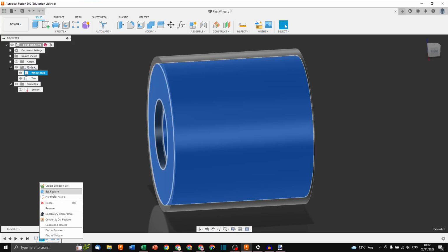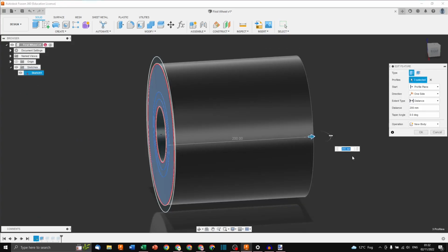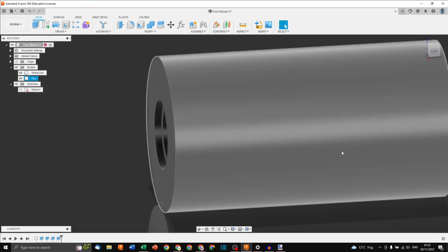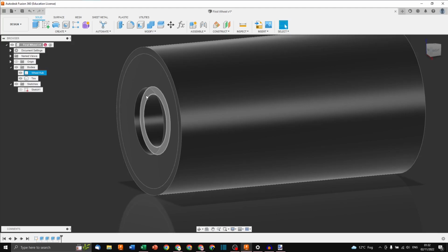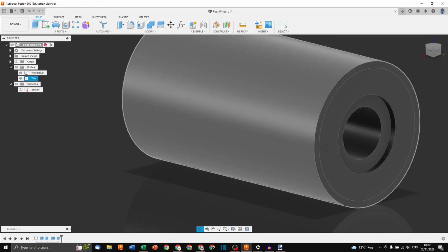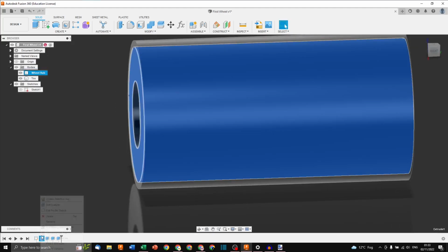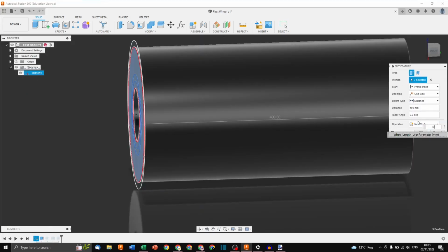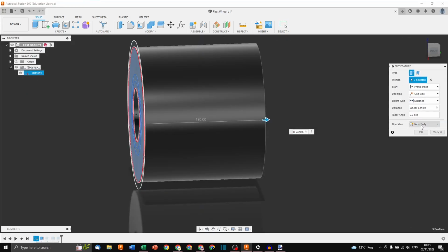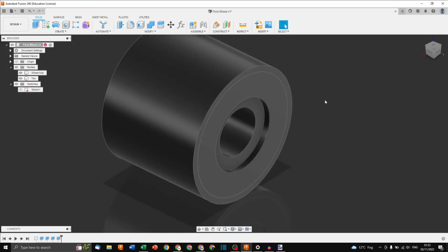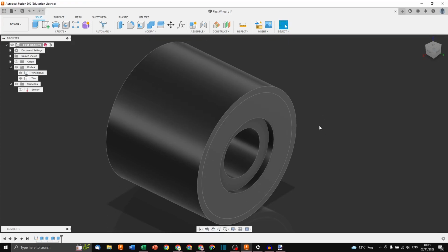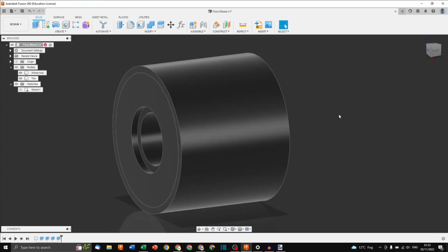So if I do it again, I can edit the first extrude and go 400. And you can see I still have a proper length tire and I still have two proper bearing seats. So let's go back to the wheel length. Perfect. And it still works. Once again, that's why you want to make parametric design. So our wheel is pretty good for now. We'll save this.